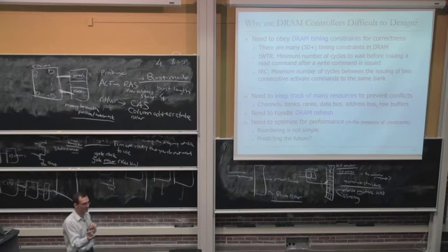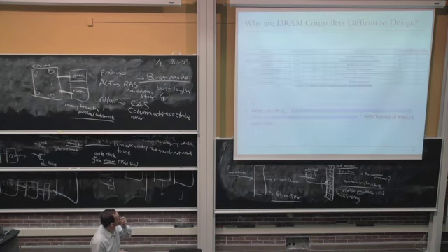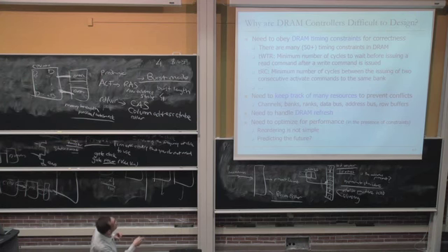You take the address of the row in the row buffer, and you need to compare it to each location to figure out whether the request hits in that row. And you need to also have a priority based on the age, right? So it's not as simple. And we haven't even talked about the more complex policies. Doing this, especially in the presence of all of the other constraints, makes it more complicated.